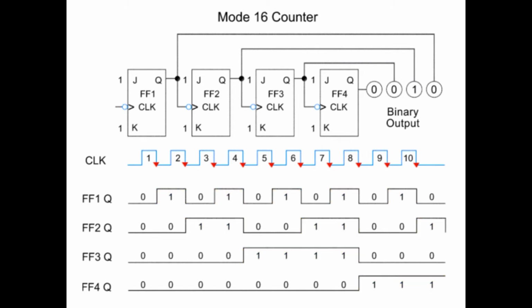Let's observe how a sequence of 10 clock pulses will ripple through a series of 4 flip-flops in this 4-bit counter. As we have shown, the first clock pulse generates a binary output of 0001, and the second, an output of 0010. As the remaining pulses arrive at the input, the third pulse toggles Q1 back to 1, with Q2, Q3, and Q4 remaining unchanged, and the output is